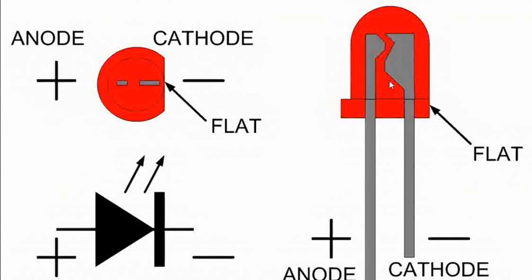We are talking about a through-hole LED. LED belongs to the family of diodes, right? So the marking, as in diodes, will be towards the cathode side. If you see the flat line that is represented, or inside, the larger part is the cathode part. This is the easiest thing to identify. You can see the flat being represented here.